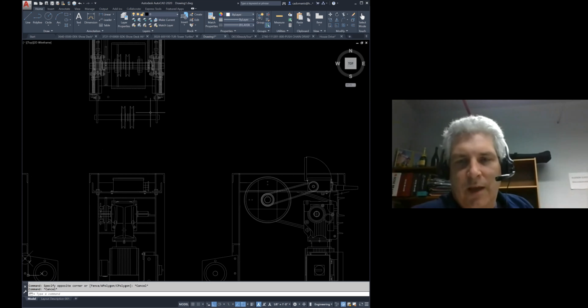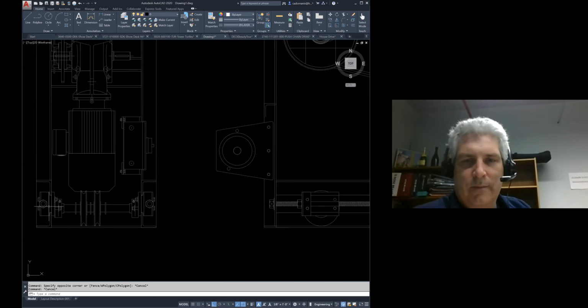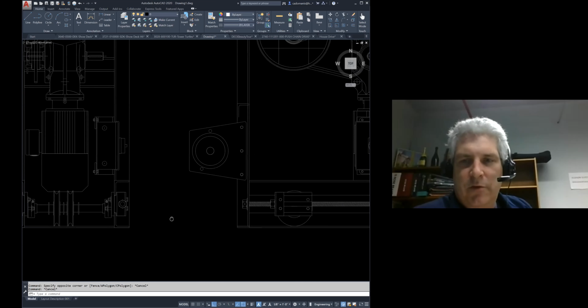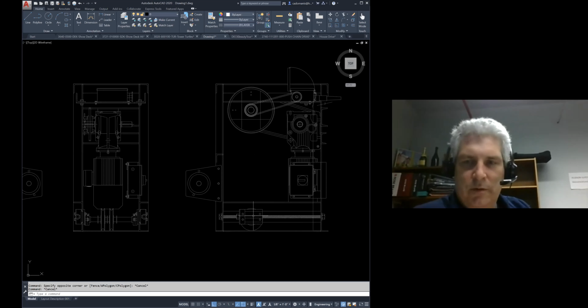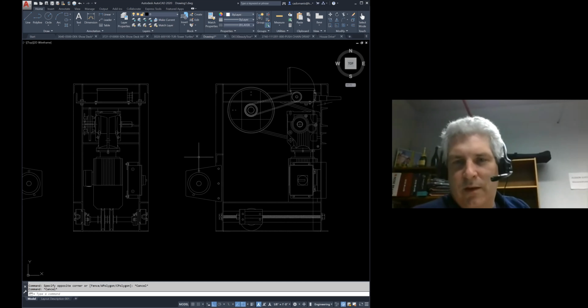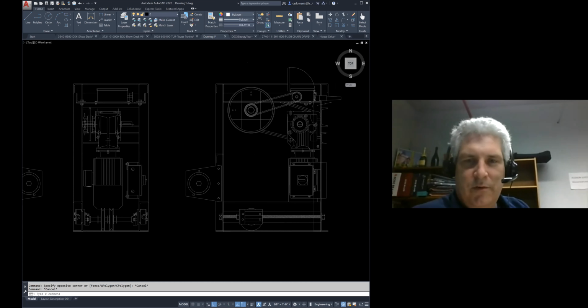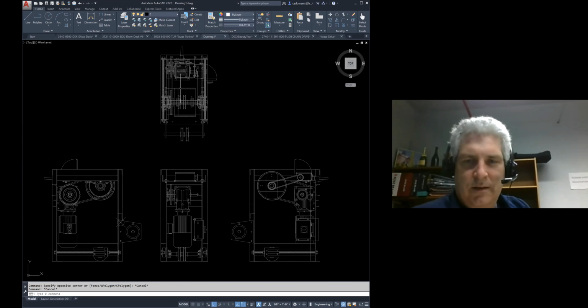In order to make that stable and work well, we want to be able to tension. And so at least in our winch, and I think you see this in many typical deck winches, there's some kind of built-in tensioning system. We have a set of sheaves on a shaft here at the bottom. And that shaft can be driven back and forth with this threaded rod. And that lets us make that loop of cable. And then by bringing those sheaves back, we can tension that whole loop. And then, different people have different styles. We have some outriggers if we need to go and divert those cables a different direction. But I think that's kind of the basic gist of it. I don't know, Loren, what else do you have to add?